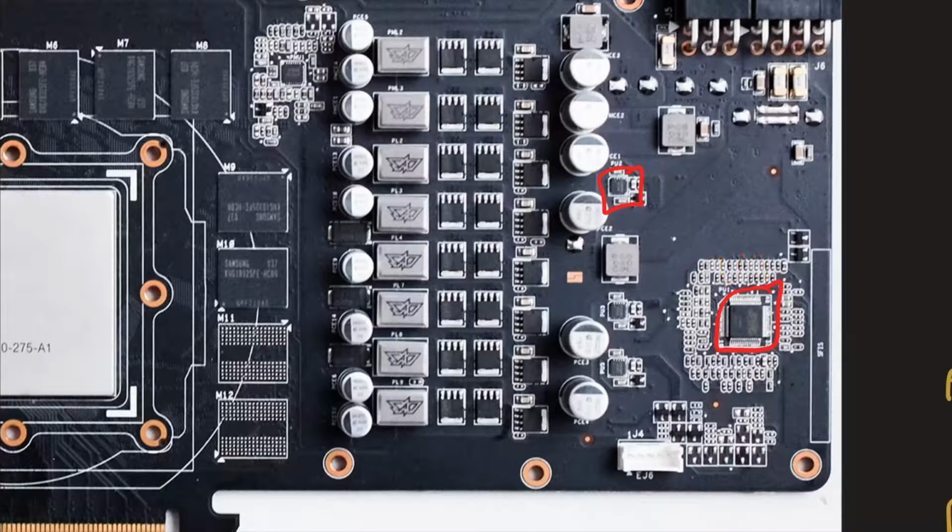But you could also, as a cost saving measure, put a PWM controller with only 3 PWM signals on there, and you could still get 6 phases, in quote marks, because it's not really actually 6 phases if you do it like this, with doublers.